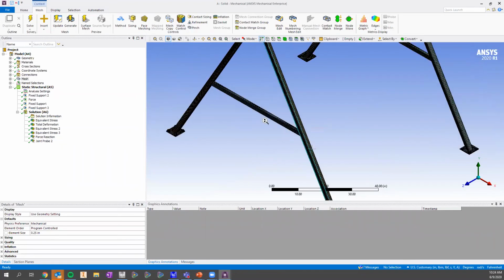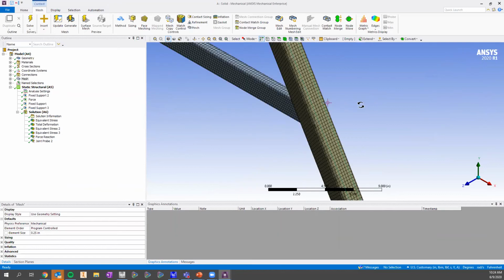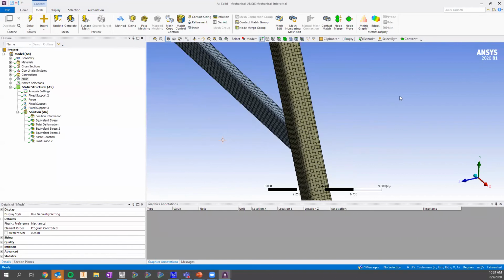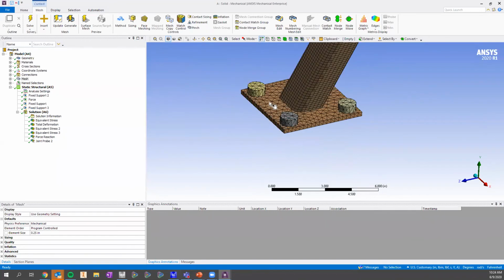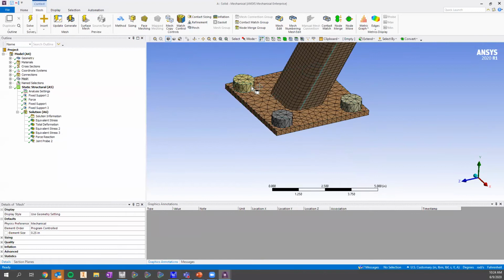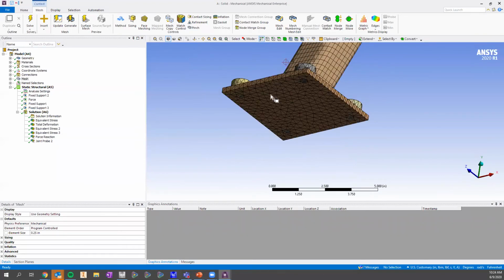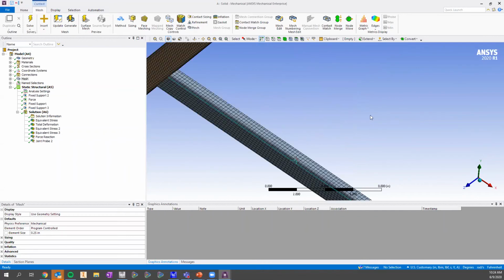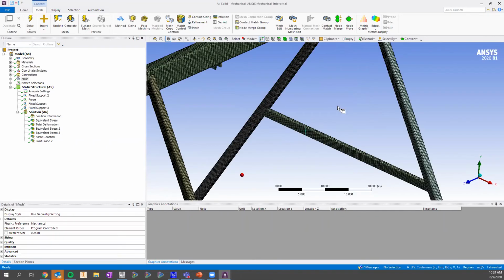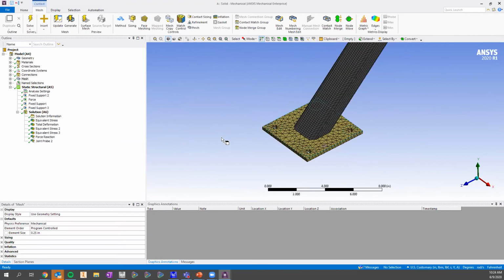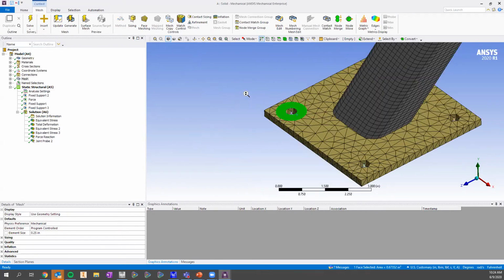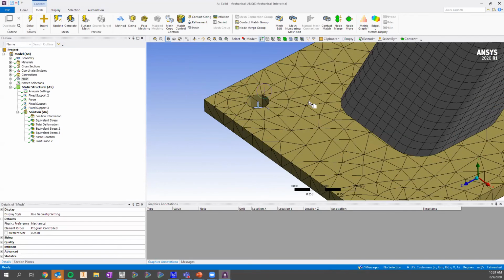There are no interferences or intersecting geometries to stop my simulation from running. I have defeatured this hardware over here so that I can apply loads onto it if I wanted to, or use it as boundary conditions. And I have also used that split surface I made so I can apply some boundary conditions and loads without that hardware there. Oh, look at that. What's this line here?